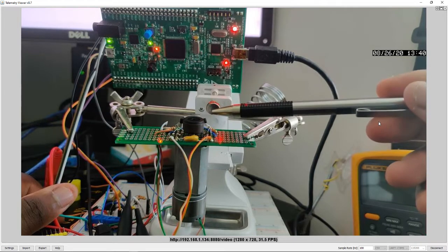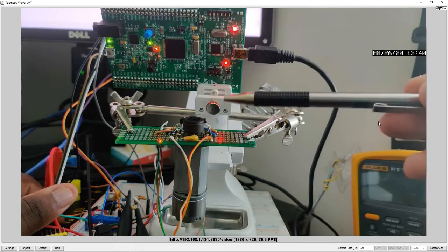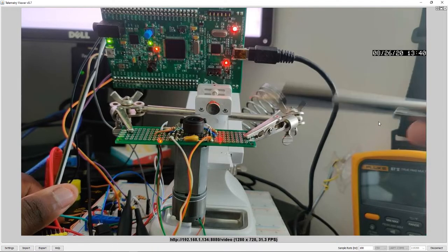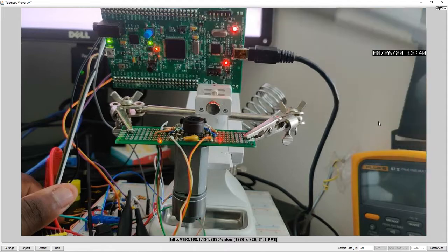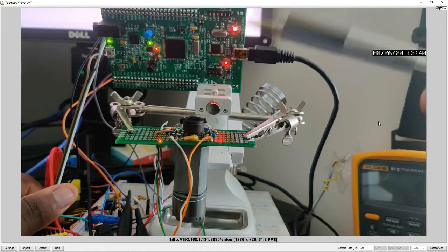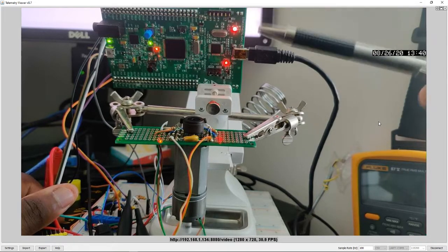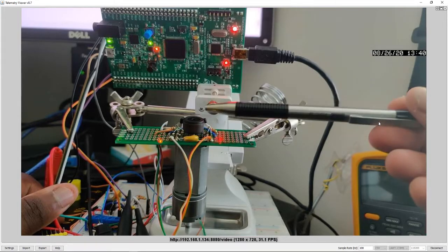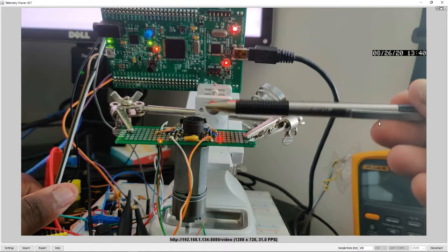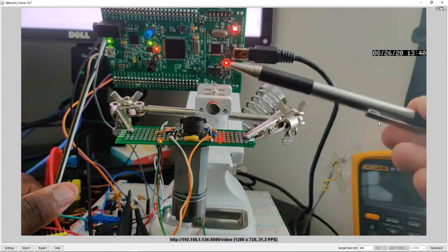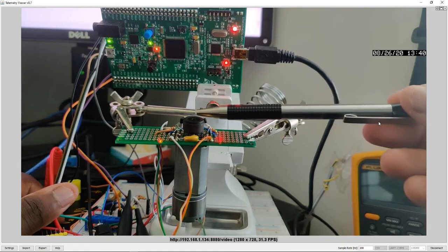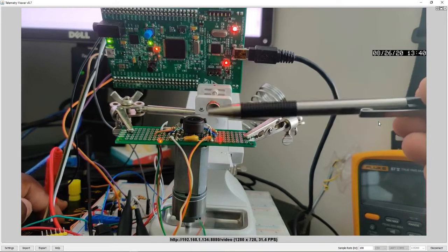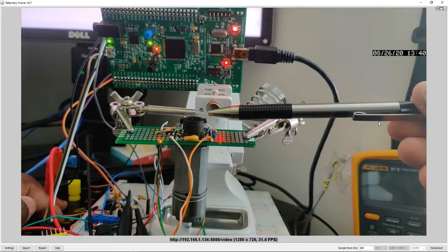These encoders are normally pulled high, and they pull low once I think it's either the north or the south pole of the magnet gets detected. I think it pulls it down. But the magnet is an 8 pole magnet. I got it from Phoenix, America.